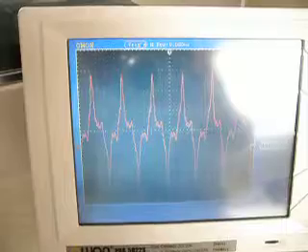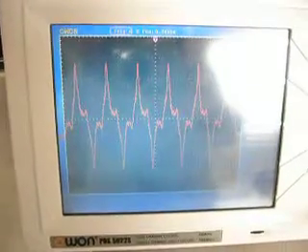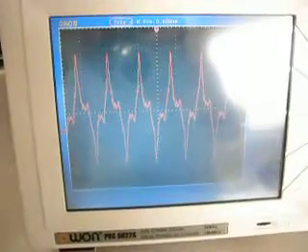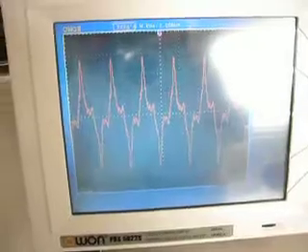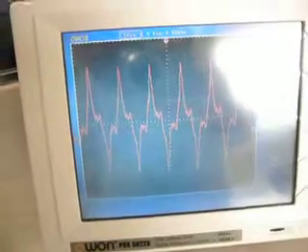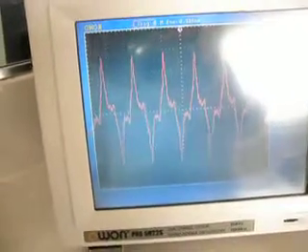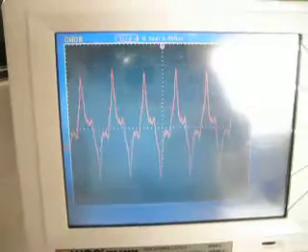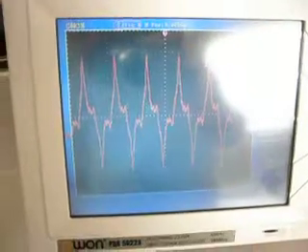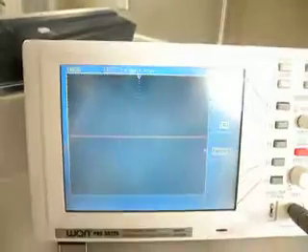as our water is currently grounded in the bathroom to the electrical ground system. As you can see, we have 6 divisions of 200 millivolts, so that's 1.2 volts peak to peak that we currently have on the water system. So let's disconnect and remove the utility connection, which is down here. So we are now disconnected from the utility system.